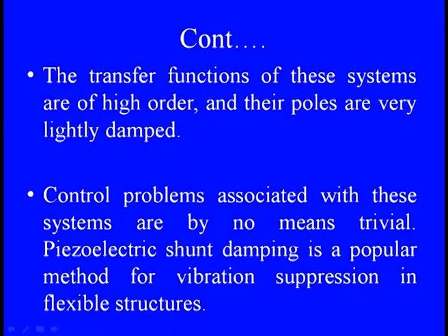The transfer function of these systems is of very high order, and their poles are very lightly damped. So the control problems associated with these systems are by no means trivial. One important thing is that piezoelectric shunt damping is very popular, as we already discussed, because whenever we want to suppress vibration of a flexible structure, we need to go with shunt damping, and piezoelectric based material providing shunt damping is one of the popular approaches in suppression of vibration for a flexible structure.